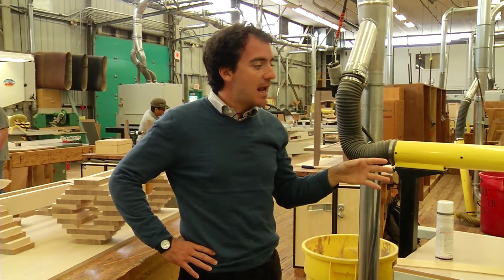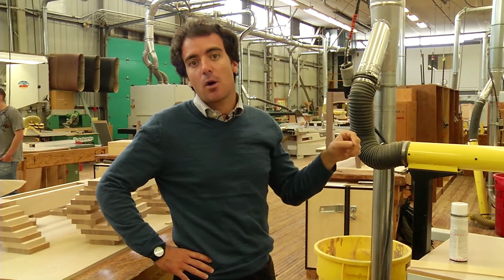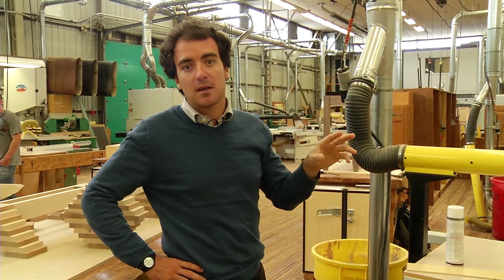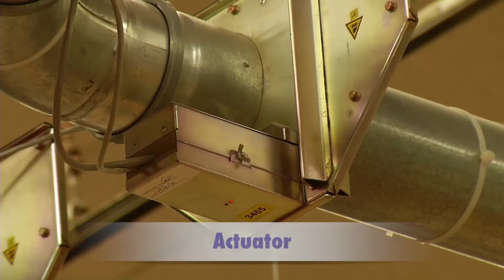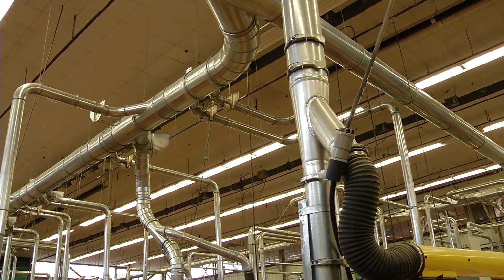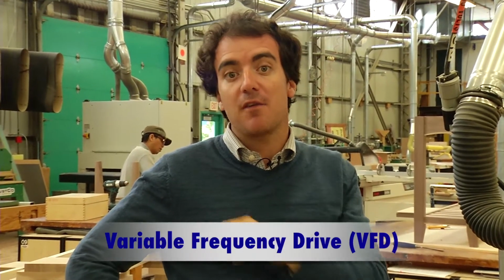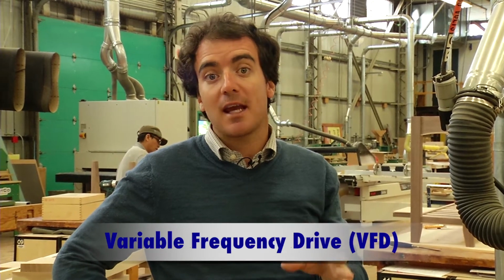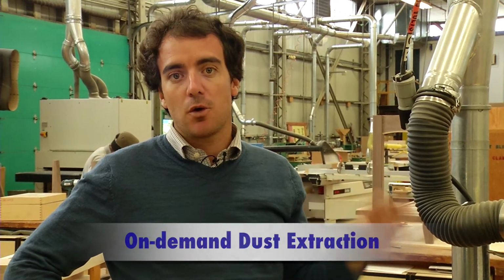And if that's the case, there's a signal that is going to be sent to our central panel that will do two things. It will open the gate that is driven by an actuator so that there's actually an opening in the duct attached to this workstation. And it will also send a signal to the VFD saying the fan needs to rotate at a higher speed because there's a new workstation needing dust extraction. So in simple terms, the new approach to doing dust extraction is on demand only. Only do extraction, only run your fan at a high speed if you need it, and if you don't need it, slow down the speed, save electricity.